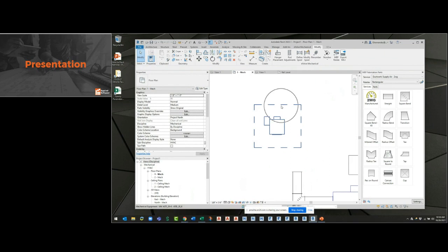But the more model lines you do, again, it's the same no matter what. You just have to find that perfect medium. Too many model lines is going to break the project, or possibly introduce corruption eventually into the family, and then into the project. So just keep it at a minimum. You don't want to draw in the vents, the brand of the company, none of that stuff. You want to stop with just as much as you need for this project.